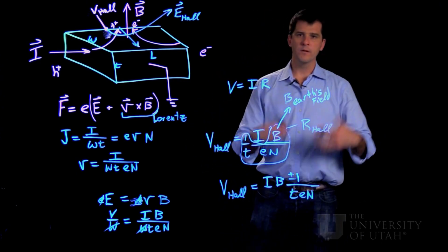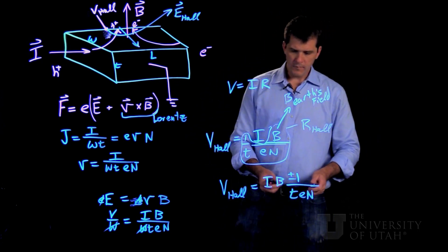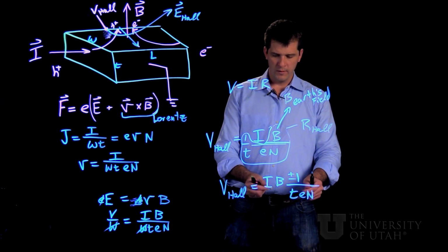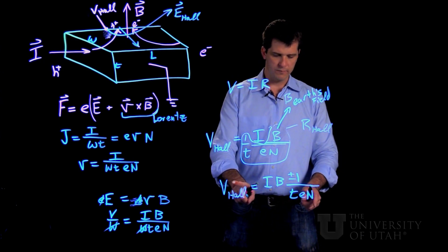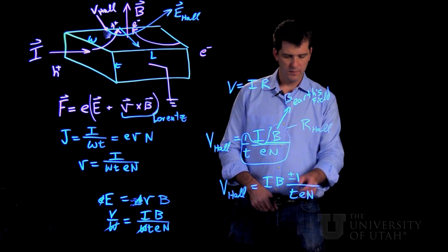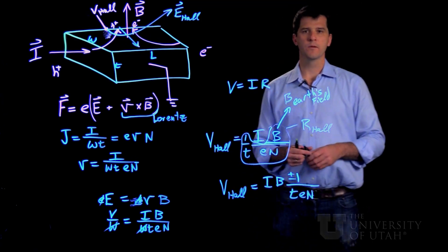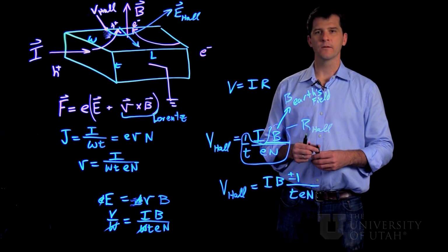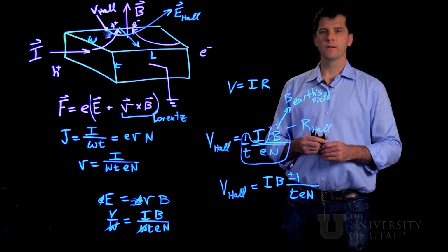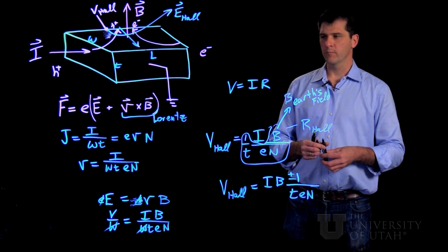And the goal, if you're making magnetic sensors, is to have a very sensitive response. And so you want to be able to measure a large voltage. To measure a large voltage, that means you actually need low doping over here. So Hall sensors are built from lightly doped, high mobility semiconductors and can detect the small magnetic field from the Earth's built-in field.